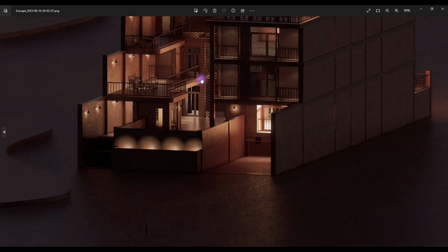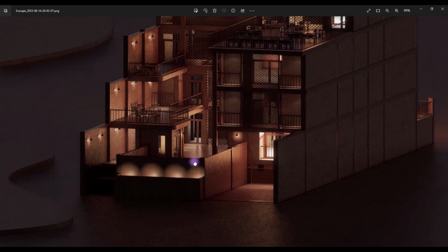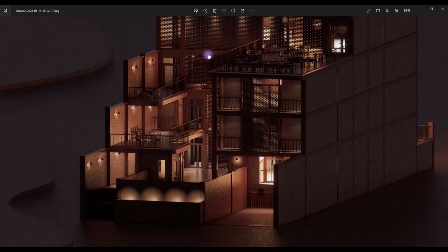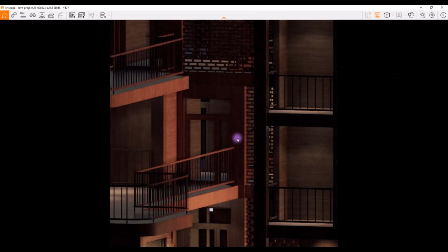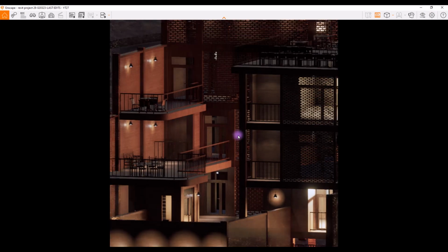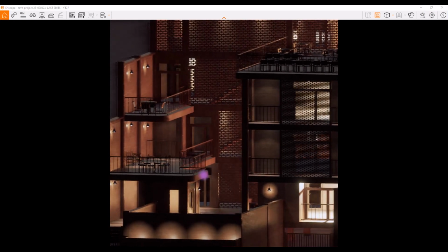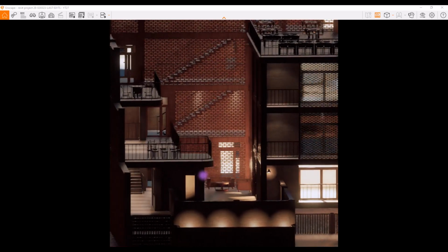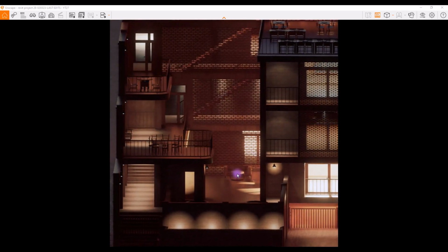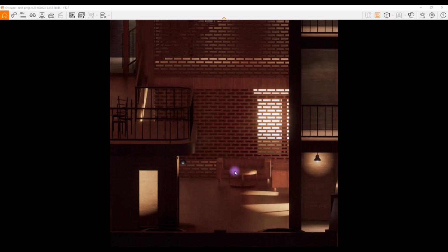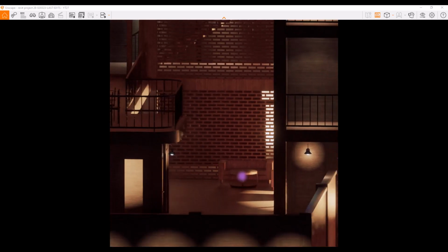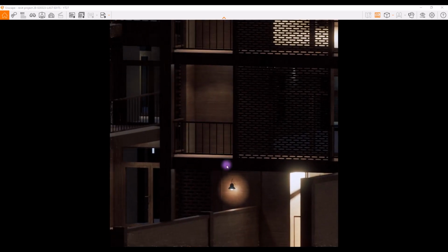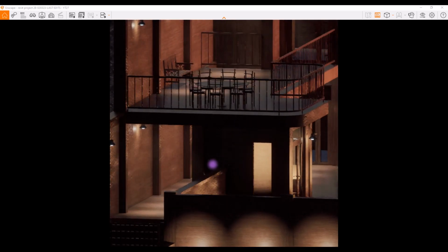In night render, you might see all of these noises in this part. This is something that we can't actually do anything about because we don't have denoiser and we can't control the quality of our light. But something that you can do is to increase the quality of your image, and that way you might see less noise in this part. And also if you increase the lighting, if you increase the overall sun setting, you can have better quality.